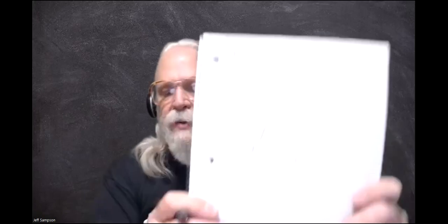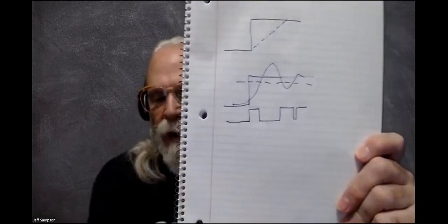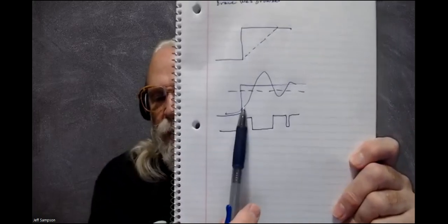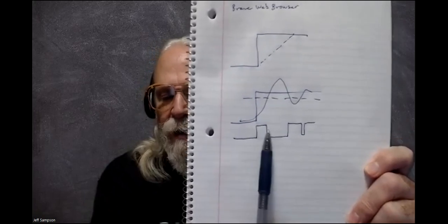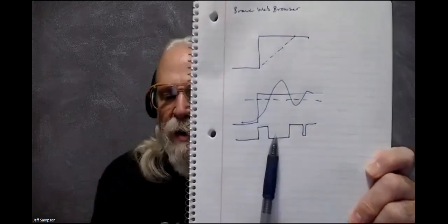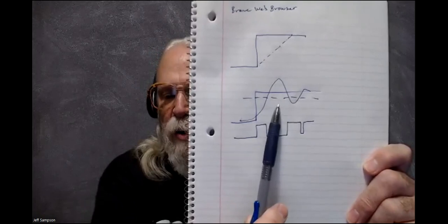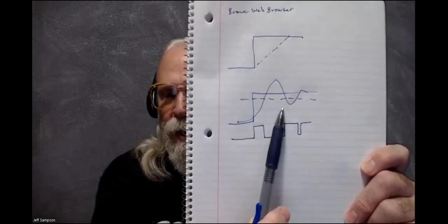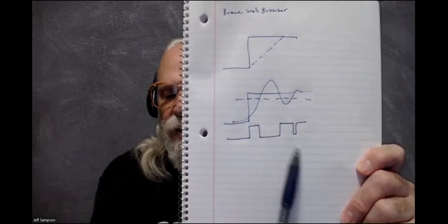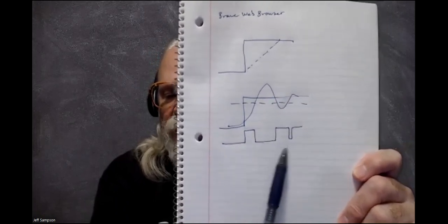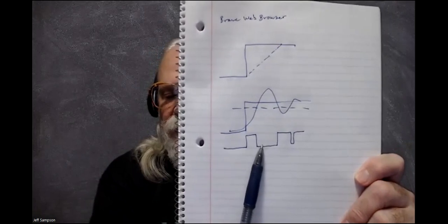It's going to do something like this, where you set your arbitrary limit, that dotted line there, and as the motor gets close to that line, whatever PWM you're putting out, you just simply set it to 0, and that kills power to the motor. So you might have enough momentum that the motor is going to keep going and hit the hard stop anyway. But at this point, you've killed the power going to the motor. So the motor is just coasting at this point.